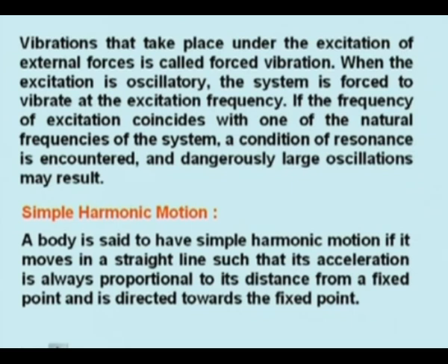Vibrations that take place under the excitation of external forces are called forced vibrations. When the excitation is oscillatory, the system is forced to vibrate at the excitation frequency. If the frequency of excitation coincides with one of the natural frequencies of the system, a condition of resonance is encountered and dangerously large oscillations may result. You may see that suppose there is a spring mass system and you apply some oscillating force.